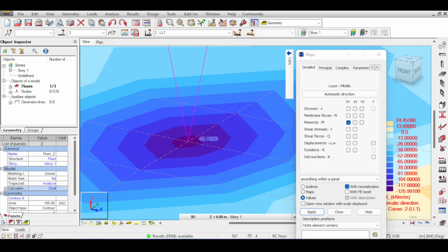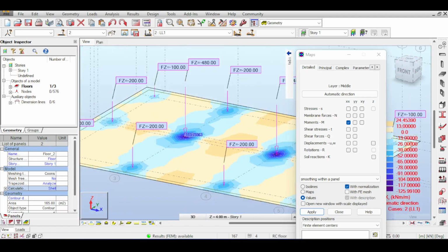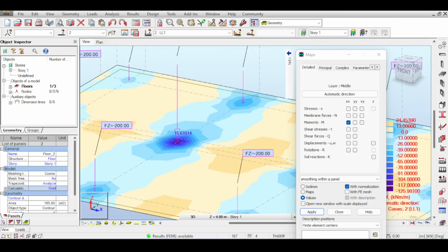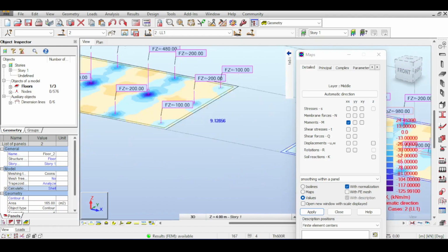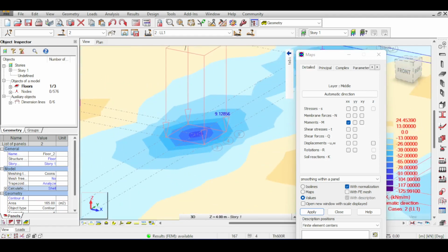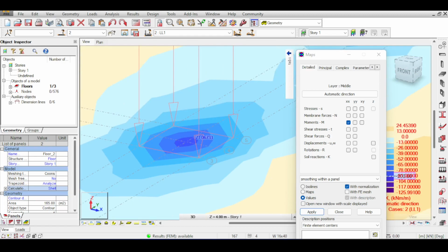So what I practically do is that I don't take the moment underneath the point load to design. No, I go a distance which is the width or half the width away of the column center, because this is a little bit more accurate, whereas this is an overestimation. The reason being, I have just showed to you this logically and without a shadow of a doubt. The reason is that your columns are not basically a needle that applies pressure on a raft. No, your column is basically an area that applies a stress on your raft.